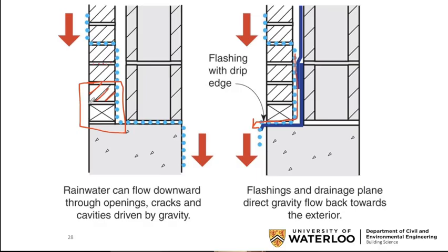But where you have an open vent and drain, as this system does right here, we put an X through it to indicate that it is an open joint. And that's the kind of thing that you might stick a fibrous baffle in, an insect screen in, etc. But it's where you want the water to go out, and to make sure it goes out, you use the flashings.